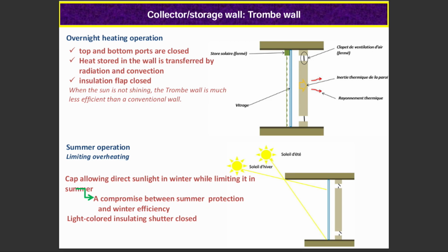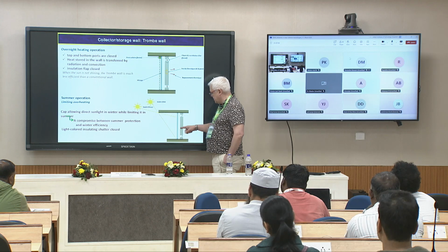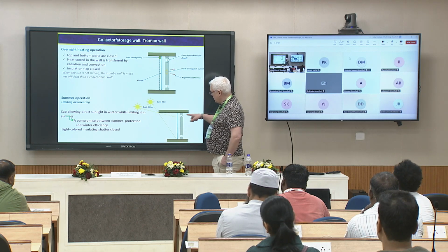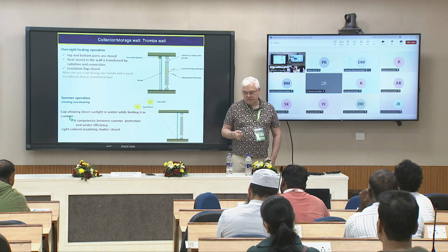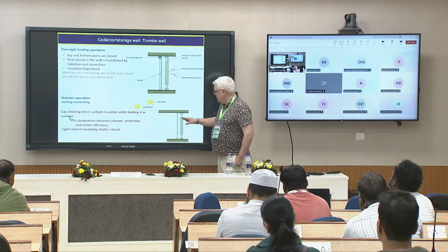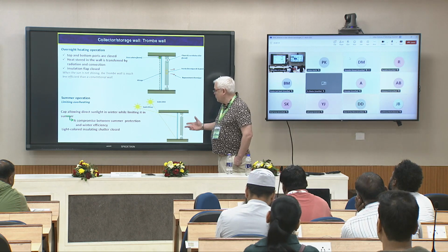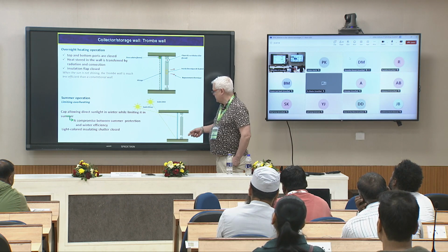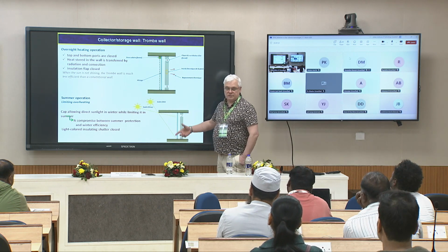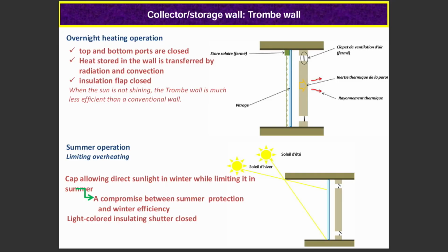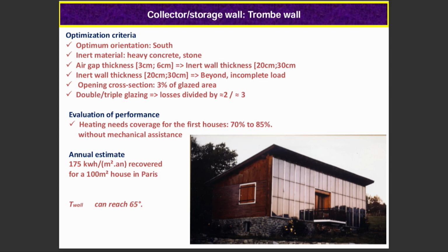Usually the cool air is down, going inside, warming and going inside by thermosiphon effect. This is the main Trombe wall, originally. There is protection, of course, for summer, because if you don't protect, or at least erase the glass, it will be too hot. So you have to add shading protection for summer.